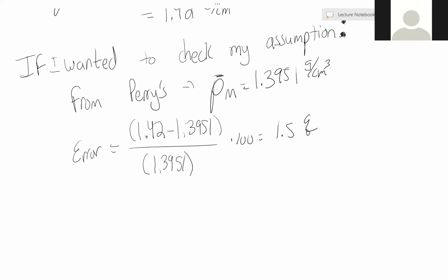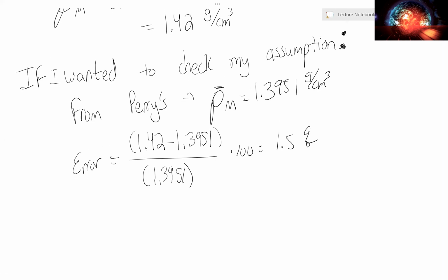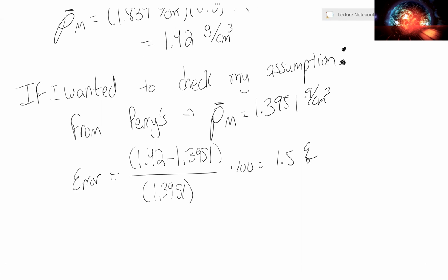Do you care which formula we use? Does that matter? That's a really good question. In theory, it really shouldn't matter, but in practice, you'll often find that doing the calculation both ways, you'll get slightly different numbers. For example, if we looked at this last example, finding the density using specific volume, you'll find that the density that you calculate is about 1.29 grams per cubic centimeter, which is drastically different than the 1.42 we just calculated.